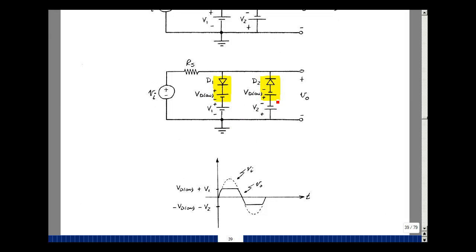Who would use a circuit like this? Well, to protect an output. Suppose you had a speaker here, and this represented the most power you could put into the speaker. In other words, the voltage was high enough that that voltage would be at the rating of the speaker. And likewise down over here. That when the input increased and the output started to increase, we would stop it from getting any bigger than a particular value to protect the speaker. It would distort the sound, but it wouldn't destroy the speaker.